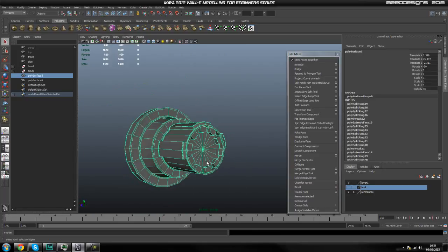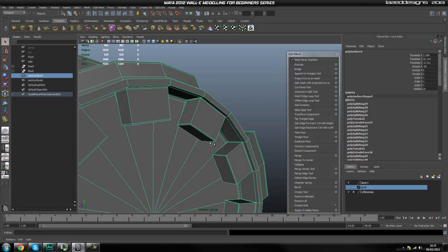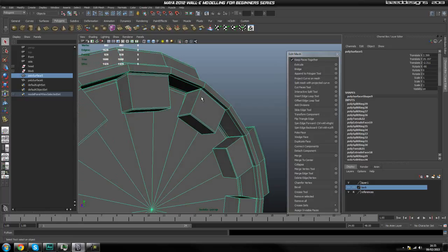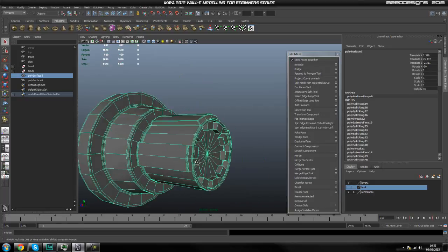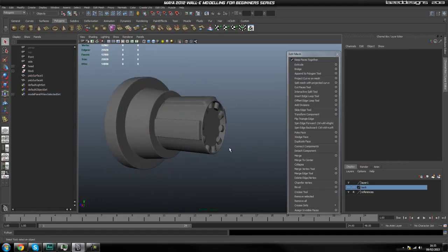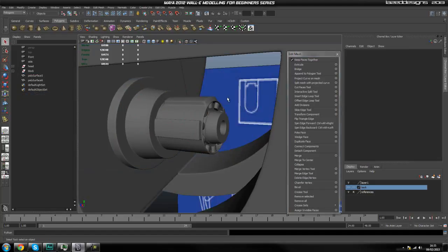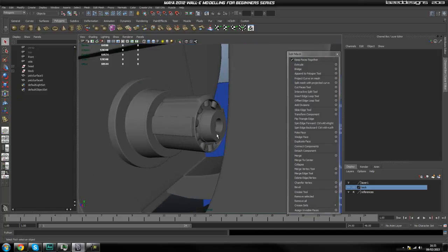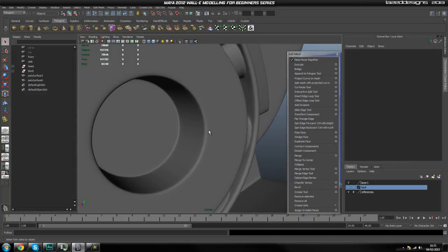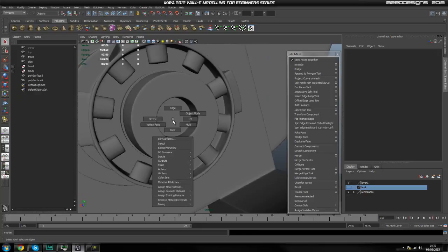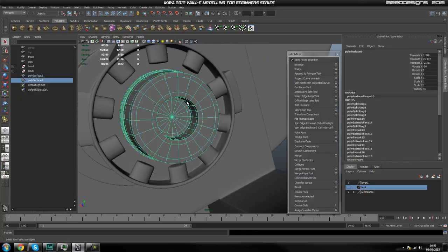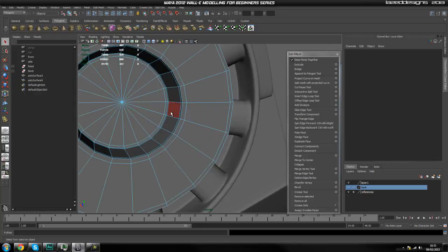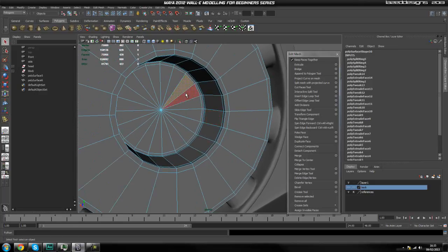Okay, if you want it to turn out to be squares and not cylinders, you're obviously going to have to add edge loops going down this way as well. So that's all I've done, and now we're going to quickly add the cable that we need. The first thing you're going to do is select this piece and unsmooth it, and then you're going to need the faces.